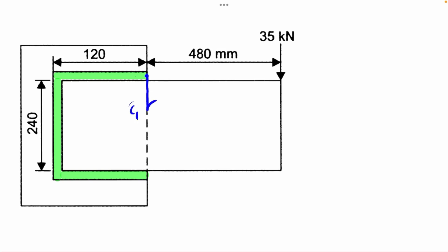So we are having the primary shear stress tau 1, which is equal to 103.14 divided by H in this orientation, and we are having the secondary shear stress, which is in a direction. If you are having the CG here, then we will be connecting these 2 points, and it will be perpendicular to the CG. We are having the tau 2, which is equal to 794.42 divided by H. We need to calculate the resultant of this one.